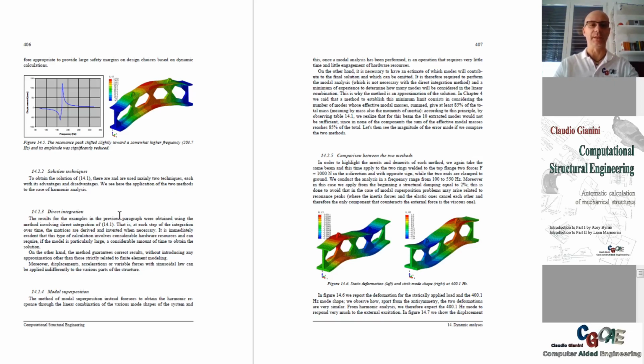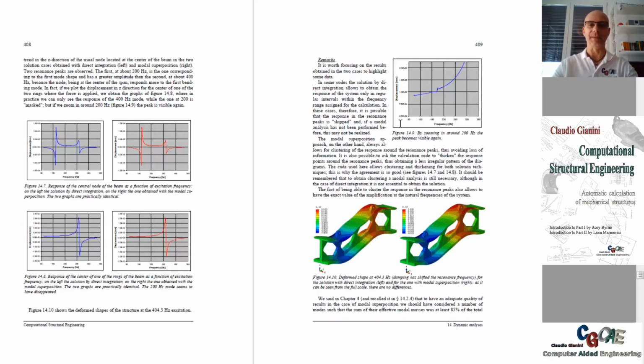Anyway, either one or the other will give, first of all, one problem, one challenge. What kind of time step needs to be used to integrate the equations? The answer, or at least one suggestion, is given in the text, one rule of thumb. And then another, the modal superposition is shown, meaning that before running the dynamic analysis we need to run a normal mode analysis, because the modal superposition technique uses the modes.